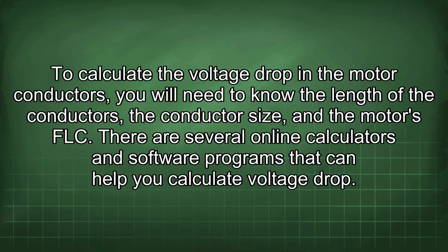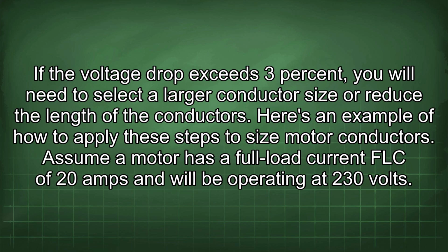There are several online calculators and software programs that can help you calculate voltage drop. If the voltage drop exceeds 3%, you will need to select a larger conductor size or reduce the length of the conductors. Here's an example of how to apply these steps to size motor conductors.